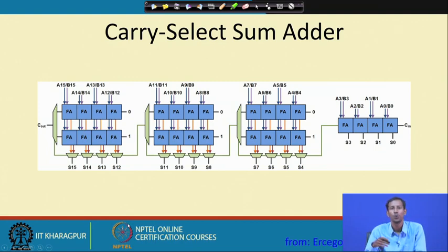Again, what we can do is select differently. In the case of the carry skip adder, we saw that if we choose the size of the middle portion larger, we can reduce the critical path delay in a better way than if we use a fixed number of bits for each of these groups. So, here also we are doing this grouping.